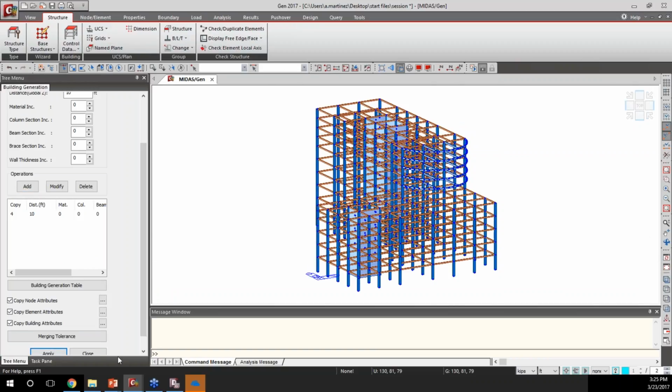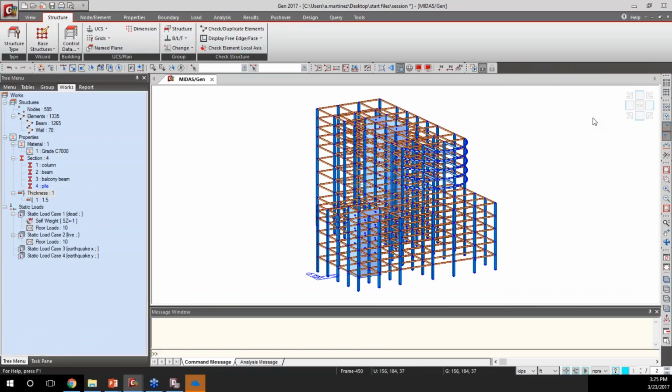And so now we have our final geometry, or final structure as it's going to be without the piles. So we can proceed now to do some analysis or apply the earthquake static loads, lateral seismic loads, and then run some analysis, some designs, even footings, and then we'll go finally back and apply the piles and the soil springs. So we have our structure.